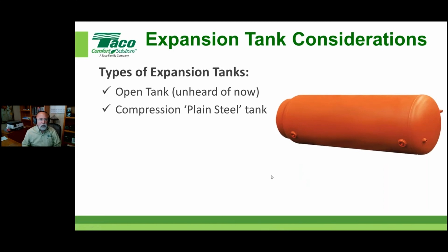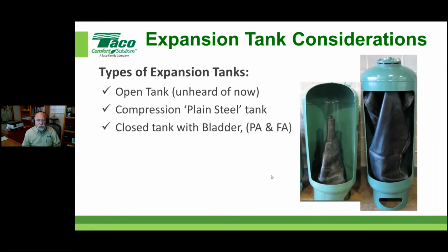So along with that, we've got closed type expansion tanks with an actual bladder. We've got what's called a full acceptance here. Okay, that just means full acceptance means that the bladder inside the tank is as big as the inside of the tank. So if you were to ever fill it completely up, you wouldn't break or blow up the bladder.